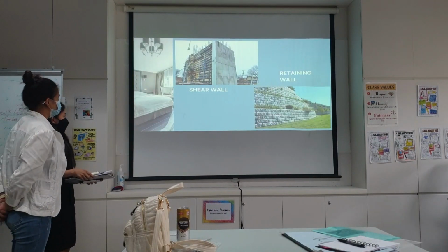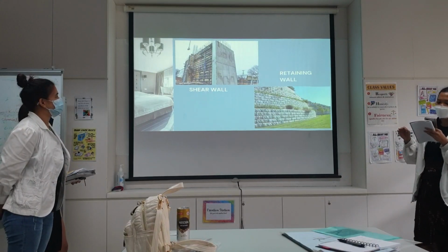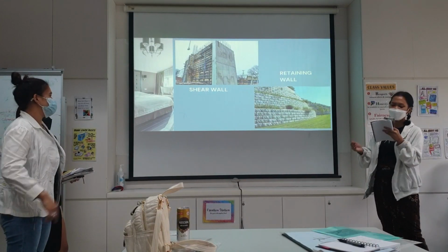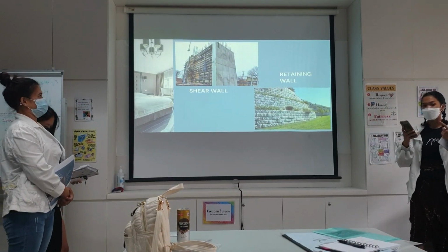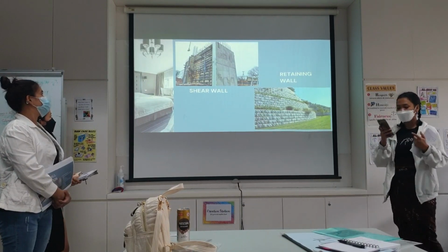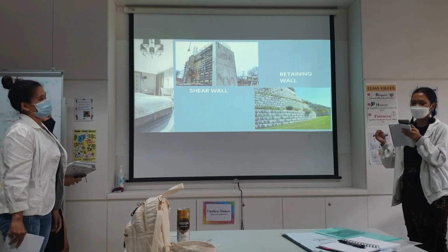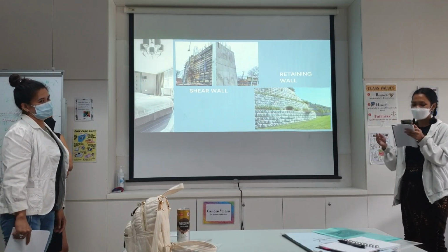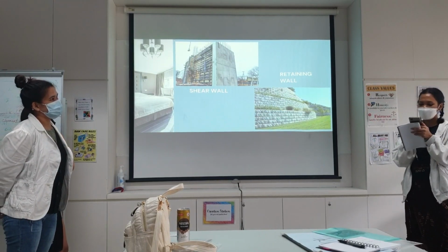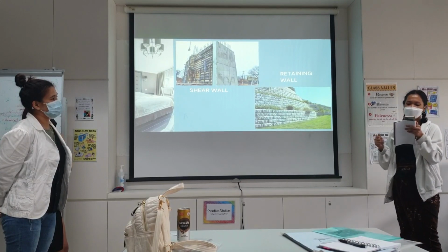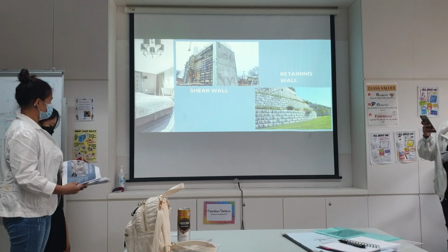The next, please. Shear wall. A shear wall is a structural panel that is made of steel brace frames which can be very effective and can resist lateral force acting on it. Shear walls are constructed from concrete or masonry which is capable of resisting lateral forces. Particularly, shear walls are of great importance in large or high-rise buildings or buildings in areas of high wind and seismic activity. It can be positioned at the perimeter of buildings or it may form a shear core supporting the whole structure.